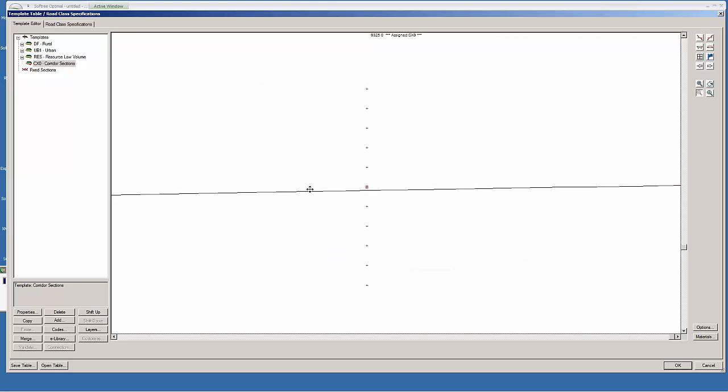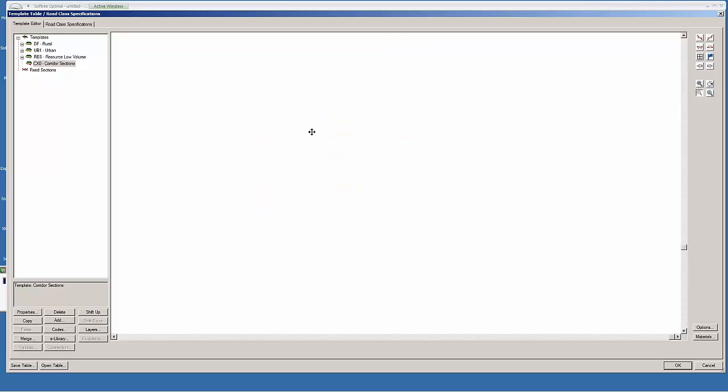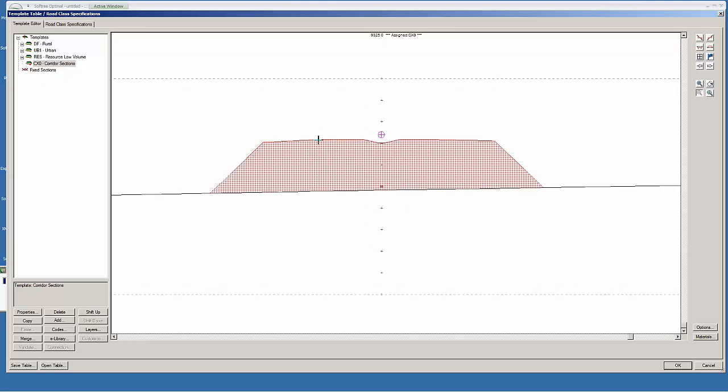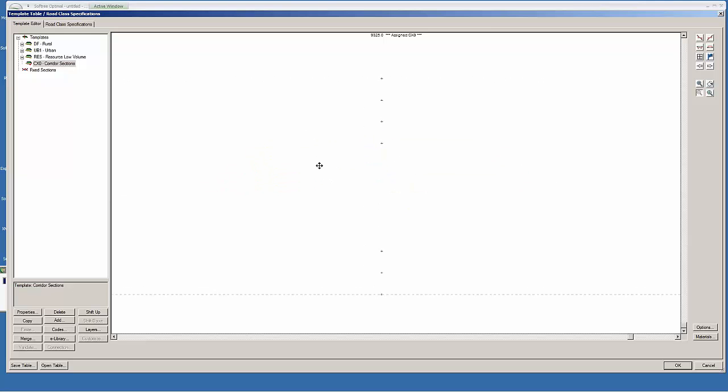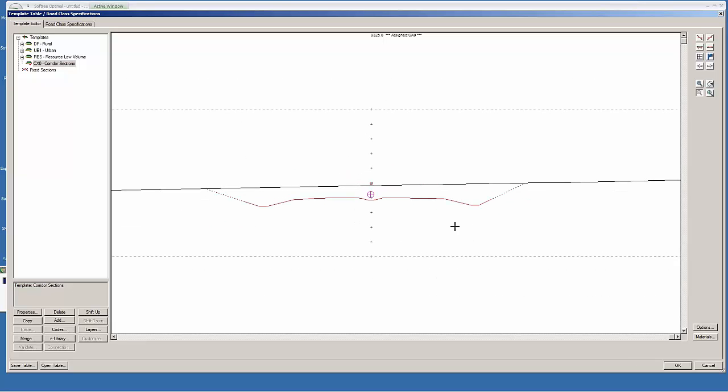It's figured out, based on what the Civil 3D assembly has done, what it should do when it's moved around. And that enables us to get a dynamic template from Civil 3D, to get a dynamic assembly without doing a lot of coding and setting target surfaces and alignments and yada yada. We get its behavior in this environment, and now we're free to do things like optimize.